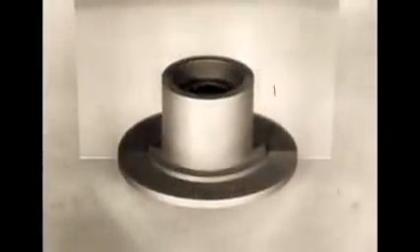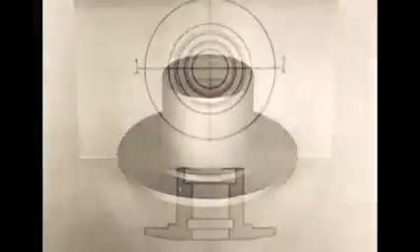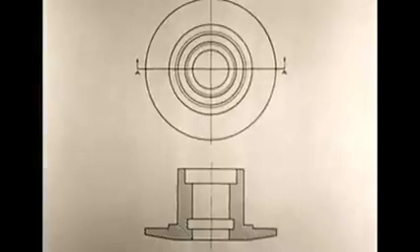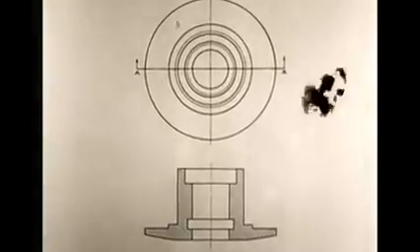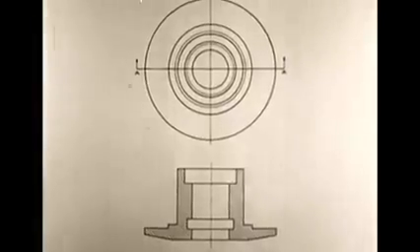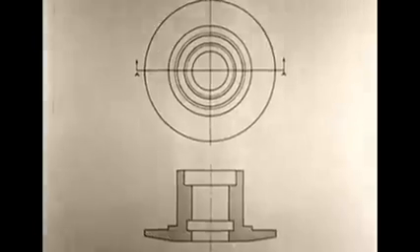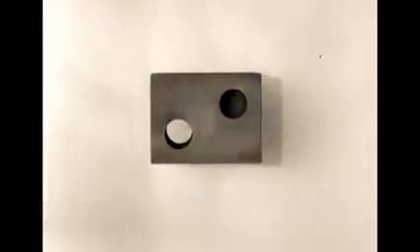Because the cutting plane passes clear across the object, this particular view is called a full section. However, you can use the imaginary cutting plane to make different kinds of sections when they are needed. For example, when you have a different kind of object, such as this, a continuous cutting plane may not reveal all the details you want to show.